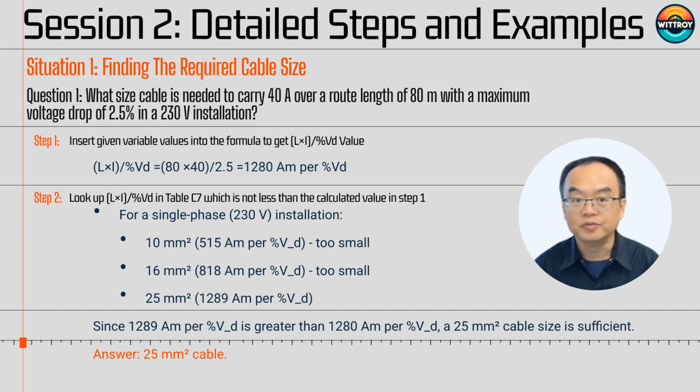Step 2, refer to Table C7. Referring to Table C7, we see that a 25 square millimeter cable's value is greater than 1280. So a 25 square millimeter cable is sufficient for this requirement. Answer: 25 square millimeter cable.